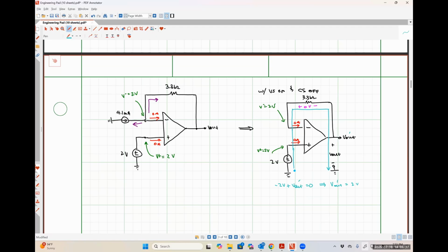So I applied a positive input signal to the non-inverting input terminal, and I got a positive output signal. Because I only have a feedback path and no other conductive path connecting my inverting input node to ground, all of my signal from my input reaches my output.